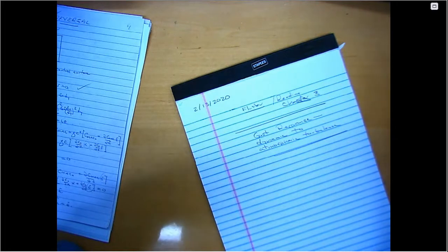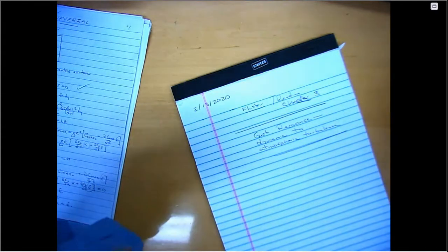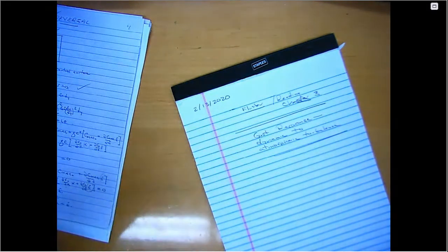The counterpart in turbomachinery, for those of you who like turbomachinery, I think they call it inlet distortion. Because in both cases you're talking about some random pressure fluctuations in the flow that lead to the dynamic response of the structure as the structure interacts with that flow. In the case of turbomachinery, it's the incoming inlet distortion. In the case of an overall aircraft running into atmospheric turbulence, it is moving the entire airplane.